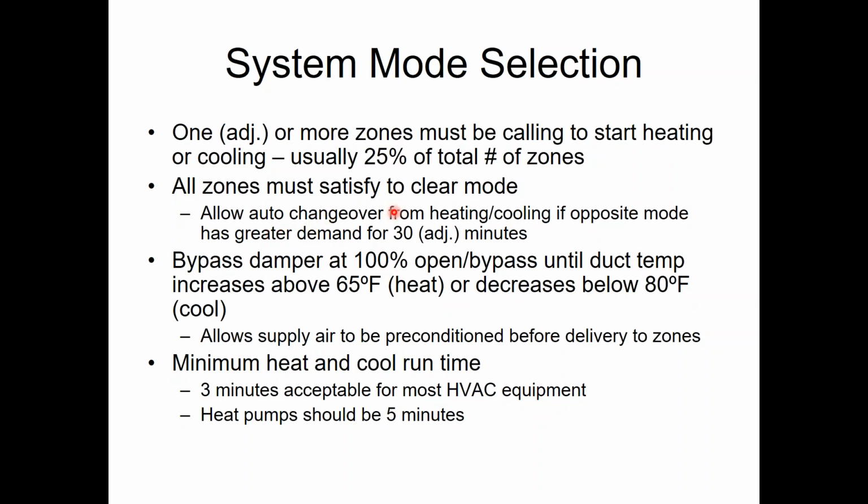You need to put some guidelines in there on how the system's going to switch from heating to cooling and which mode it's going to pick. I can't have somebody asking for heat and somebody else asking for cooling. Well, I can have them asking. They just can't both get it.